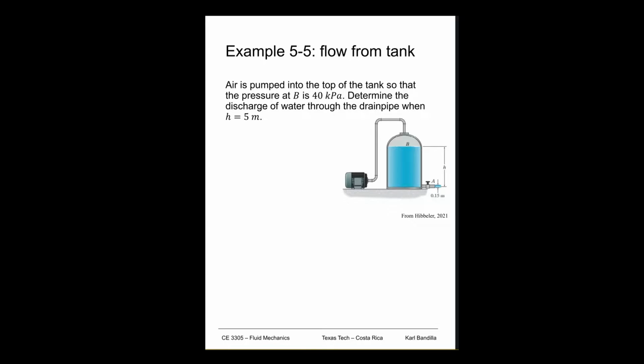And what we'll do is we'll use Bernoulli's equation, and we'll take something up here, call that point B, and we'll say the streamline goes something out here and then out there, right, until point A. So that's all good. Now if we want to use Bernoulli's equation, of course, we have to make sure A and B are on the same streamline.